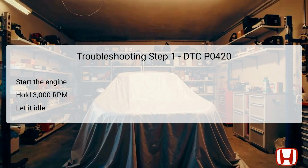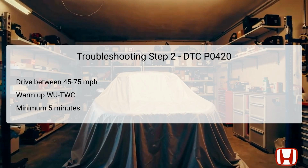Carefully monitoring the engine's behavior during this step offers insights into the underlying performance issues that may be impacting the catalytic converter's efficiency. In the second troubleshooting step, the technician is instructed to drive the vehicle at a speed between 45 and 75 miles per hour, maintaining this speed for at least 5 minutes.